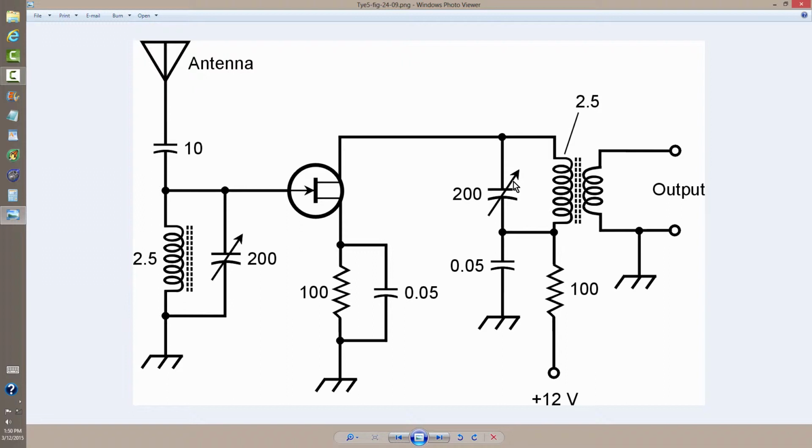I forget exactly what the frequency of design is, but there's a formula for determining the resonant frequency of an inductance-capacitance resonance circuit, either series or parallel. And that formula, the viewer mentioned, is of no practical use. It's fine in theory. Well, it is of practical use in one sense. It'll give you an idea of the component values you're going to need in order to obtain resonance at a desired frequency.